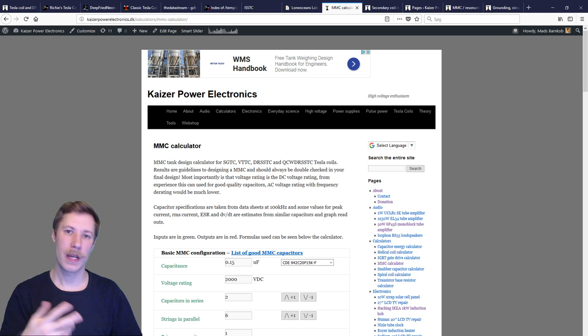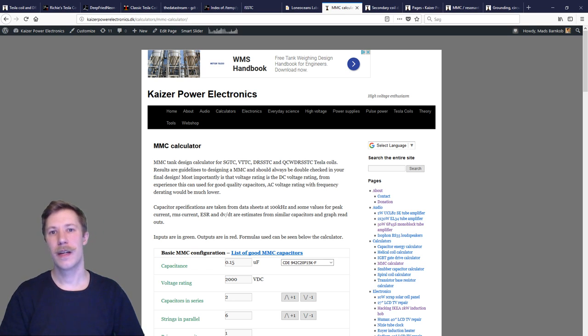So if you have two layers against each other, you have 1200 volts per turn in insulation. So if you're using a relatively thin wire, you would have some 100 kilovolts of insulation resistance at 20 centimeters coil. So the varnishing of the coil is not really to prevent arc overs as much as to keep the windings in place, because different temperatures will expand both the form and the copper wire.